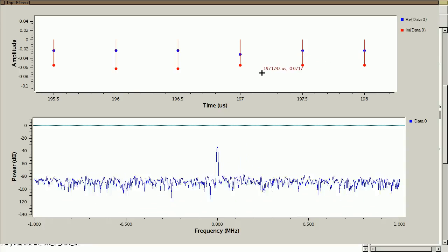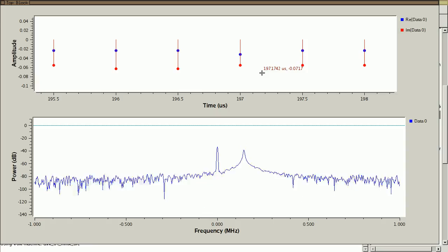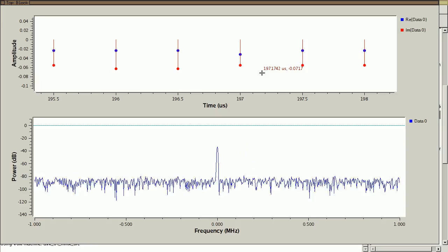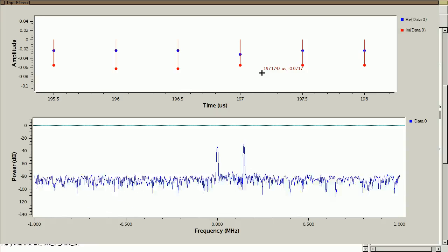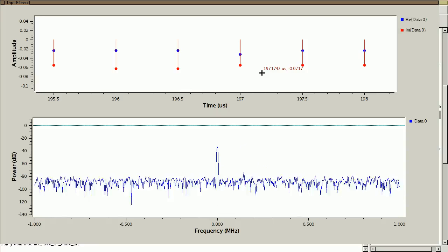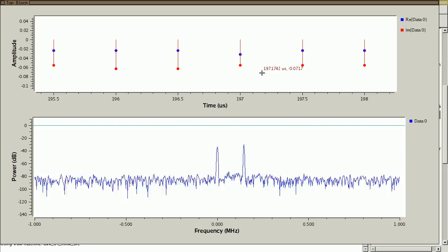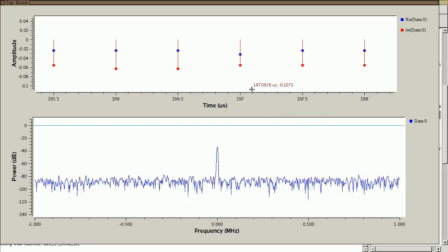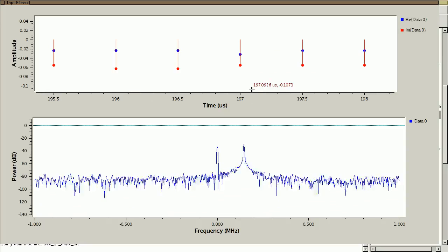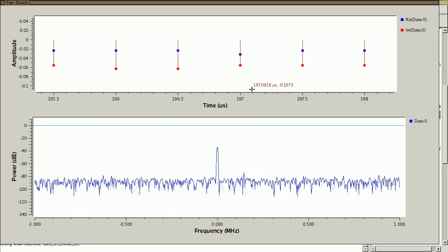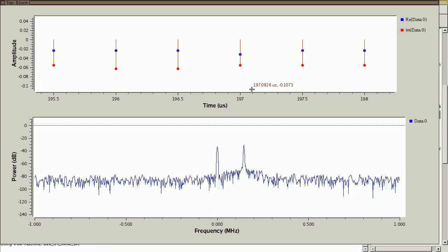And we could actually amplify our signal in the digital domain. Let's think about how we would do that. How would you make a signal stronger in the digital domain? Before we even take this waveform and give it to the HackRF, can we scale these values up? Sure we can. We can scale samples by multiplying them.